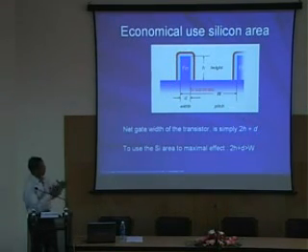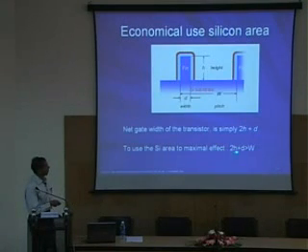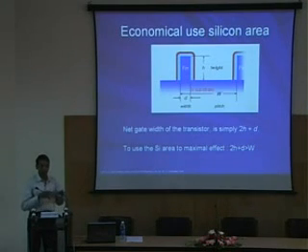If I had to pack too many of these FinFETs on the surface of the silicon wafer, then obviously the 2h plus d has to be much greater than this w. That is, I had to pack these FinFETs much closer. And it is a possibility. We can actually do that using the existing photolithography techniques.